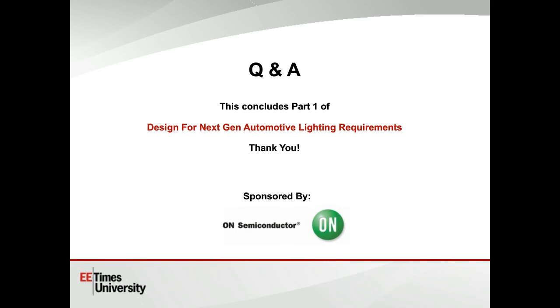ASIL level B is what people are starting to assign as the category of functional safety for lights. Of course it's not as bad as, for example, steering controls, but it still does require a level of testing and design to mitigate against failures.